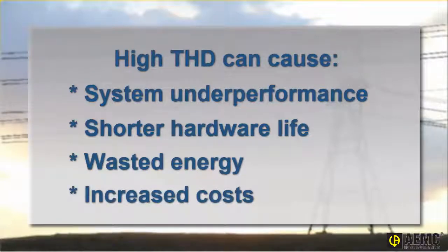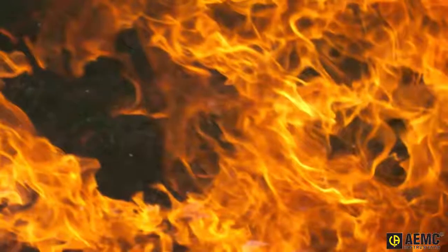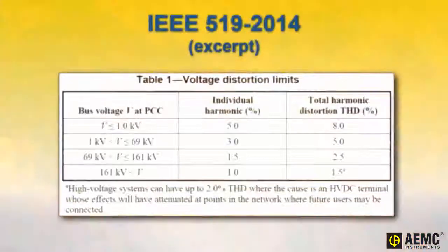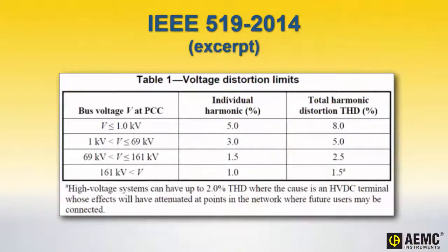In extreme cases, THD can increase the risk of personal injury to operators and damage to facilities. THD can also raise regulatory considerations. A number of guidelines exist, such as IEEE 519/2014, that define how much harmonic distortion is allowed for certain types of facilities. Strict adherence to these specifications can be an essential business requirement for many organizations.